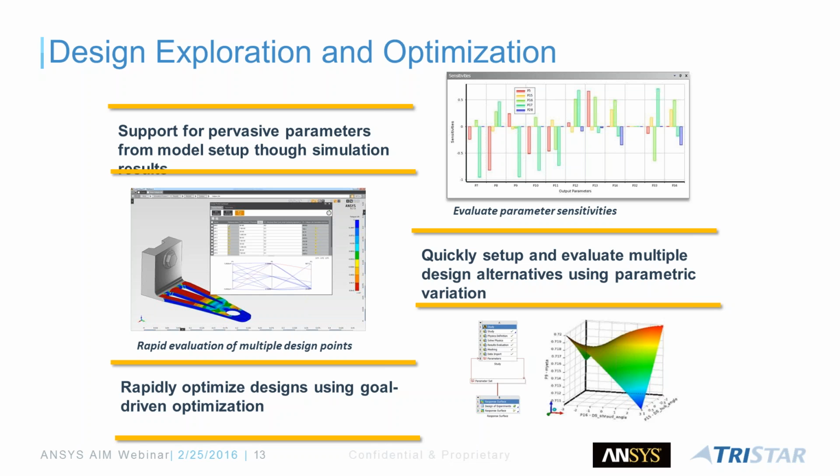It could be from a CAD software that you're currently running that you can expose within Ansys AIM, or it need not be, it could just be a neutral file, and still you could use the SpaceClaim design engine that's working behind the scenes of Ansys AIM, which allows you to parameterize that design and then run what-if scenarios. This is one of the most important things in my view. When you're a designer or an engineer, you don't want to go back, change the design, and rerun the analysis. You want the analysis tool itself to help you with those types of what-if scenarios.